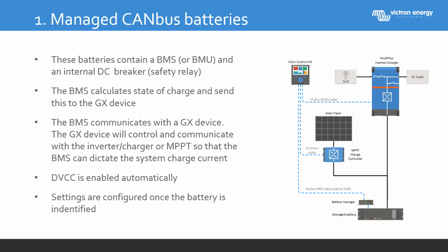And a lot of these settings are linked to a feature called DVCC, distributed voltage and current control, and that dynamically allows the battery to control the charging, to ensure that all the cells are balanced and they're all working harmoniously. So that's quite critical. Lithium-ion batteries, we've learned a lot of that in the last 7-8 years. In a lot of ways, they're totally different to lead-acid batteries, but there are some similarities: they do need regular charging. So the settings are very important in that space.